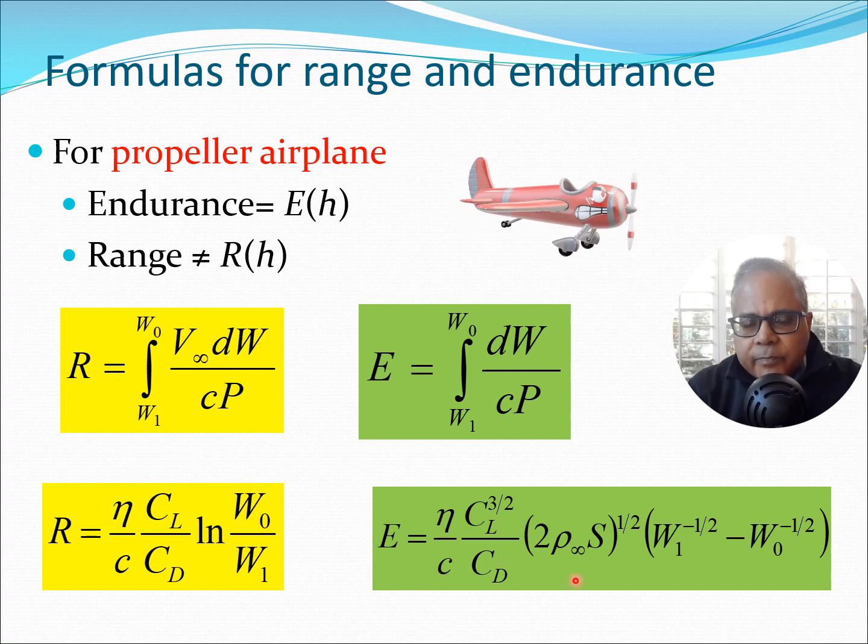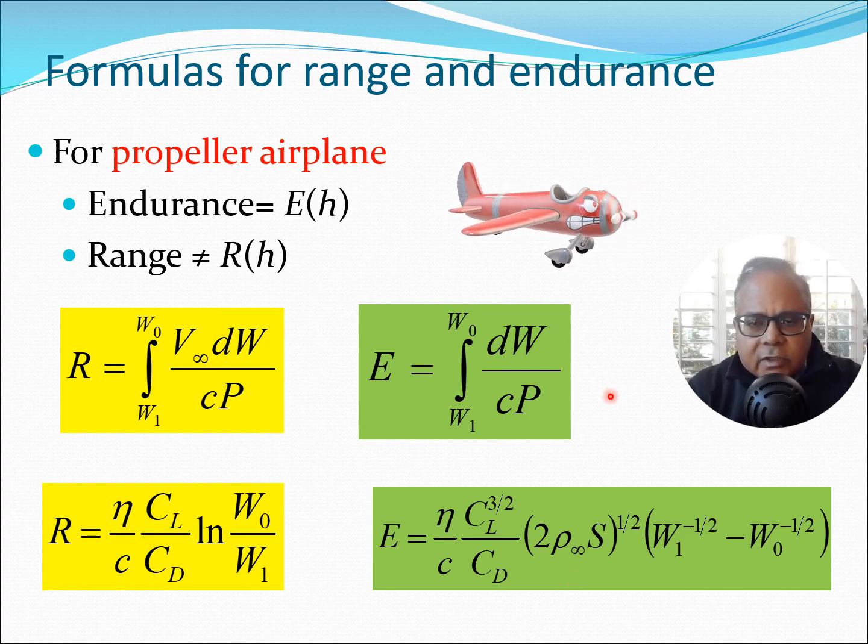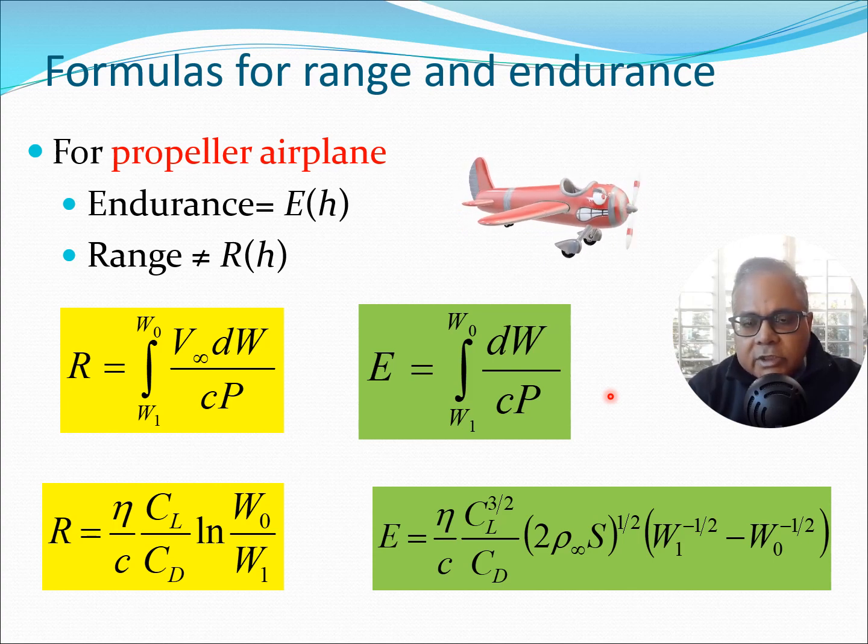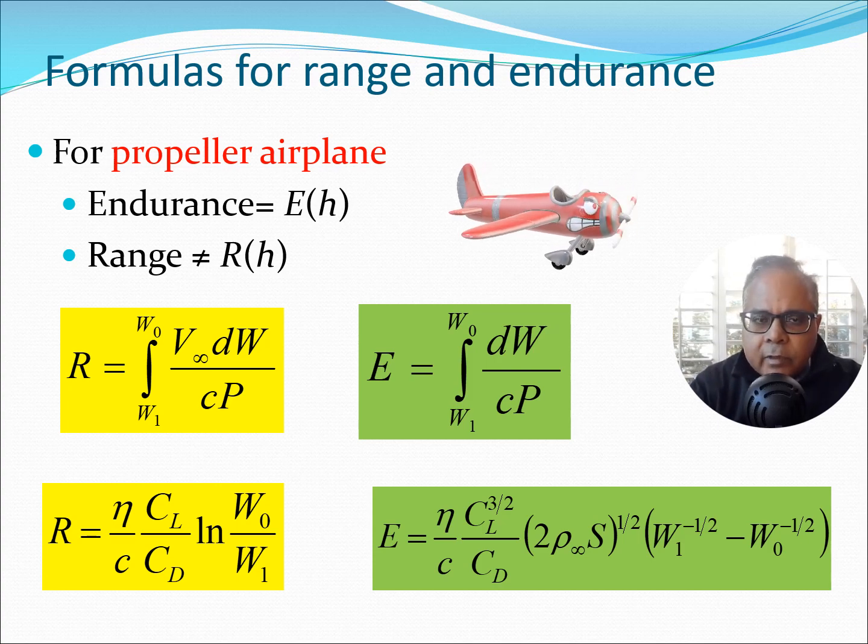We can see here that endurance would be maximum if you fly at a very low point, and that's often the case that when you are designing a propeller aircraft, you typically look for missions where you fly low. Maybe you fly short haul between two cities. Maybe you are designing a UAV, which is mostly going to loiter at low heights so that it can loiter around the ground and so on. And so, wherever such kind of situations are involved, where you have an endurance driven mission, then you can consider a propeller if you are going to fly at low altitudes, because that's going to maximize the endurance.